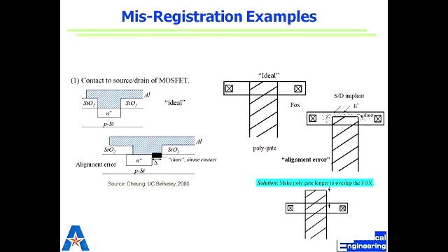If we have designed a circuit to offer certain resistance, and that resistance doubles, what happens to that equipment? It heats up, right? So there's power loss, there's energy loss. What does that heat result in? Failure, right? Ultimately, I'm going to burn down this contact. First step, contact resistance increases, which means there's much more voltage drop occurring in that device, which would mean it may burn up one day, right? So it results in failure. The technical word is failure of device.